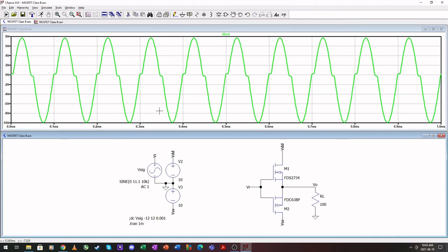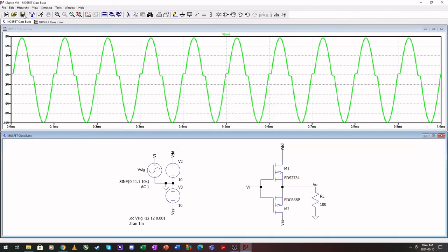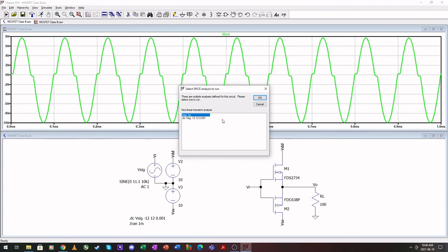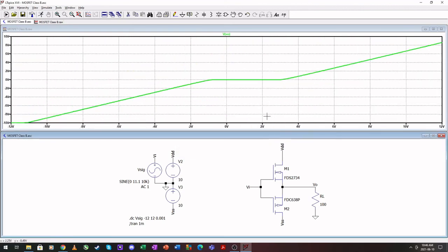It's not even balanced anymore. Okay. So you need to be careful and select your MOSFETs to match. They really need to match a lot. So if we look at the voltage transfer, 1.1 here, 3.3 volts right here. Okay, so don't ever get caught in that trap. Match your transistors.